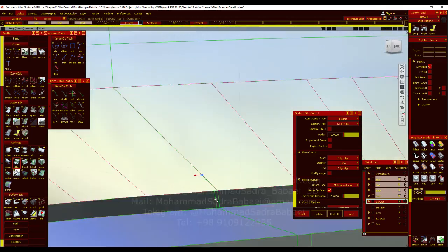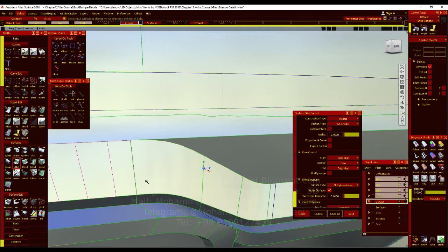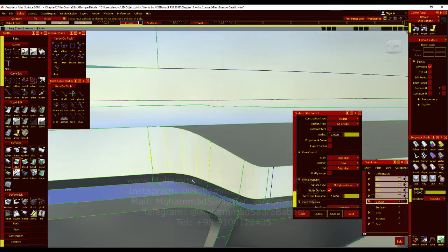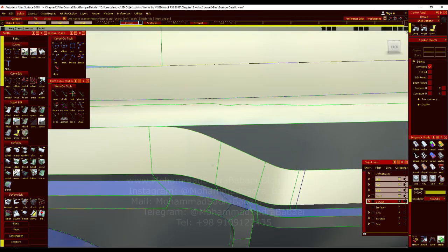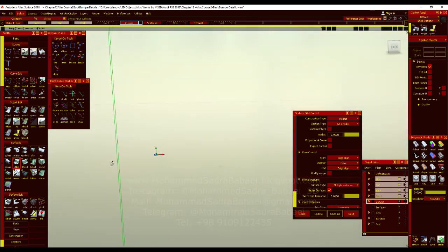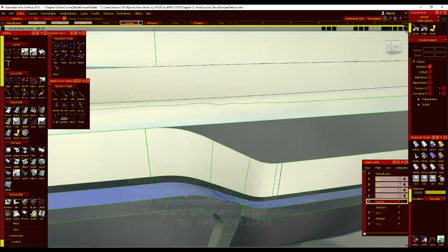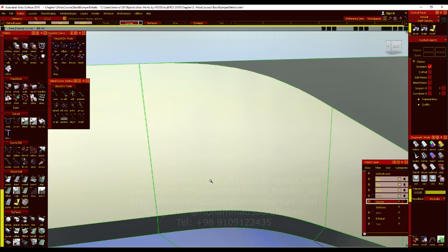We don't have a surface here, we're gonna click on this surface, but this one, okay, we have a little surface here, but it's not colored red, and I should add another revise here. We have only a tail surface here, it's not a middle surface, so I should just use the align tool to connect these surfaces.